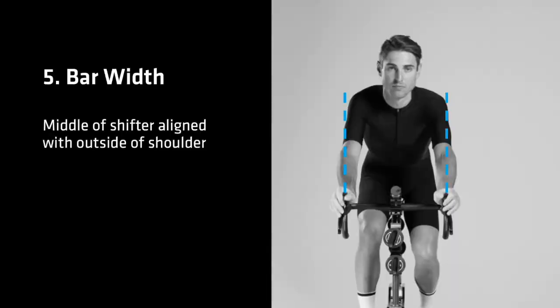When riding a road bike, the handlebars need to offer structural support for the upper body. Bar width should place the hands just to the outside of the shoulders. Have the same shape handlebar in the fit area in multiple widths with a loose pair of shifters. This way the fitter can actually show the rider what the proper width feels like.